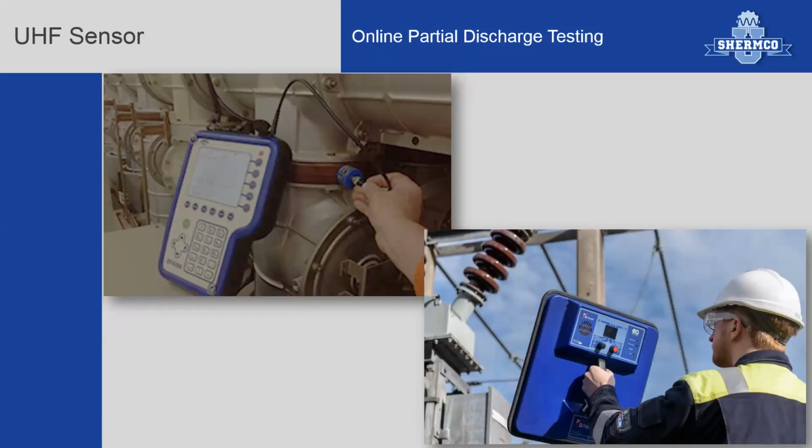The UHF pulses are going to be emitted from the site of the PD defect and will spread in all directions through the air and through most materials. However, the signal cannot travel through metal. Metal enclosures will shield the UHF emission. The signal can escape, however, through tiny cracks or gaskets and or seals, and then re-spread out into the air.